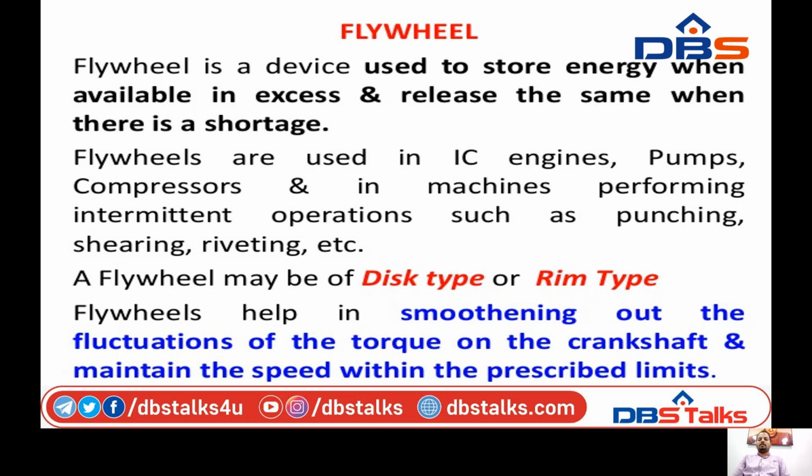These flywheels are used in IC engines, pumps, compressors and many multi-purpose engines performing intermittent operations such as punching, shearing and routing. A flywheel may be of a disc type or a ring type. In most cases we see flywheels of the ring type.